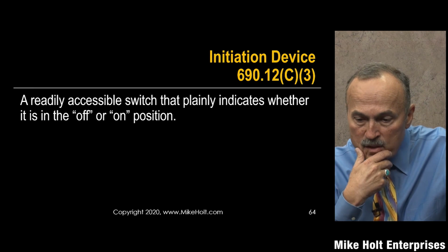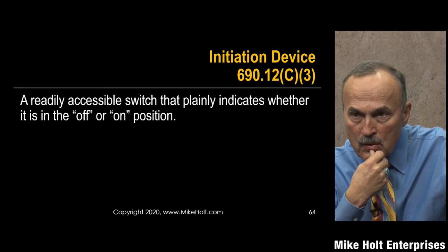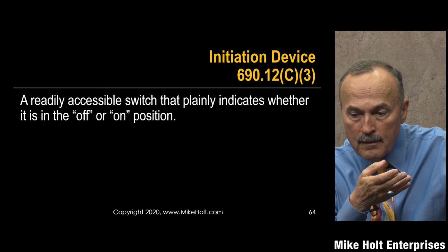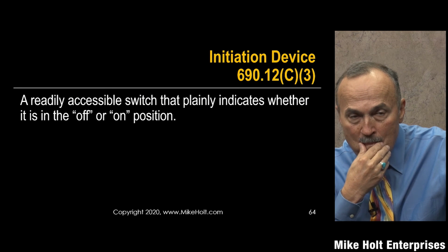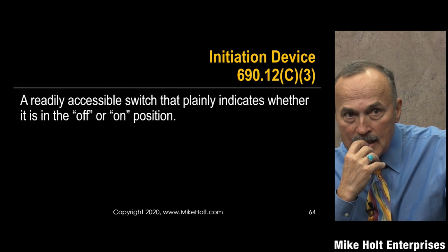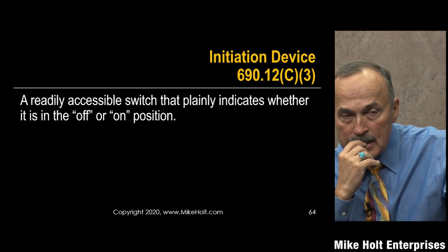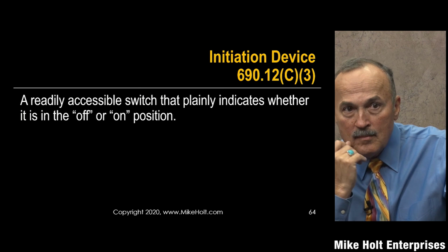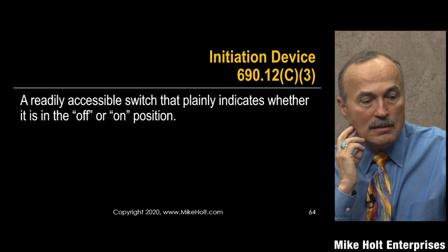One second. Let's read the language here. Readily accessible switch that plainly indicates whether it's in the on or off. Does it say on or off? No, they don't indicate. Well, some do, some don't. There are push buttons that do indicate on and off. So I'm saying, don't rule those things out. Find one. Find it on the internet today, sometime. Motor control on-off buttons. They're out there. I don't think it's an on-off button.